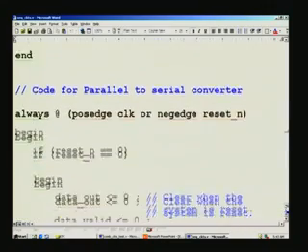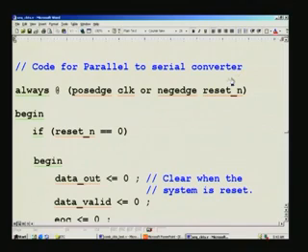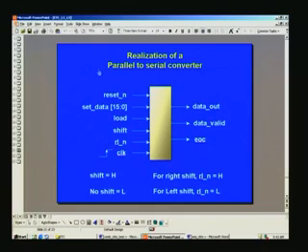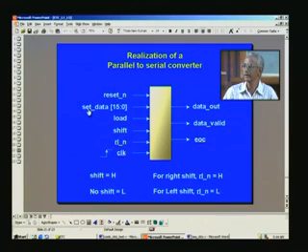And next we had taken the parallel to serial converter, and this is what we had in the parallel to serial converter. We have a power on reset or system reset, and whatever value you want to serialize, you have parallel information that can be entered into a shift register inside this box through a 16-bit data bus. Whatever data you want to serialize and send out, you can load through this, provided you assert a load input.